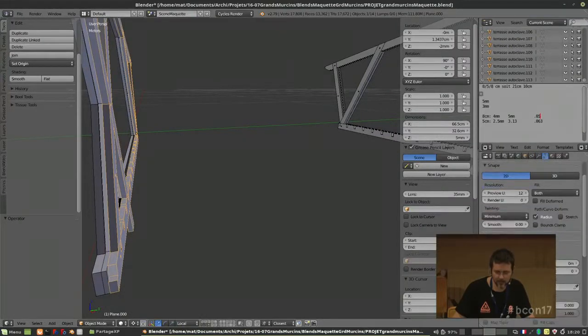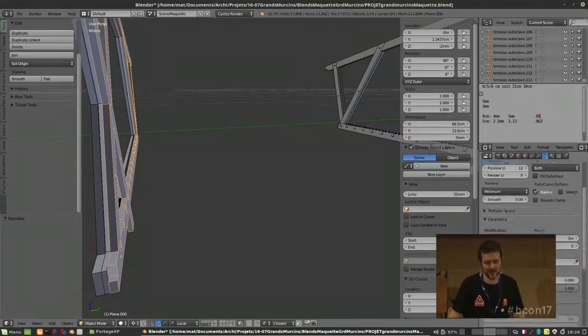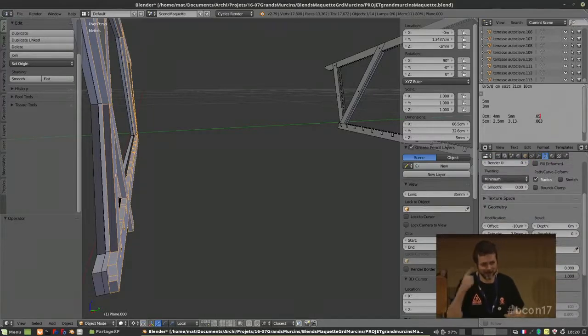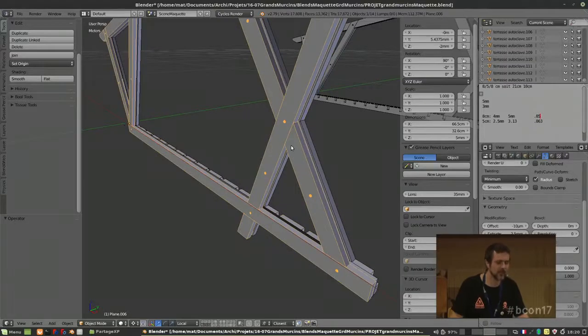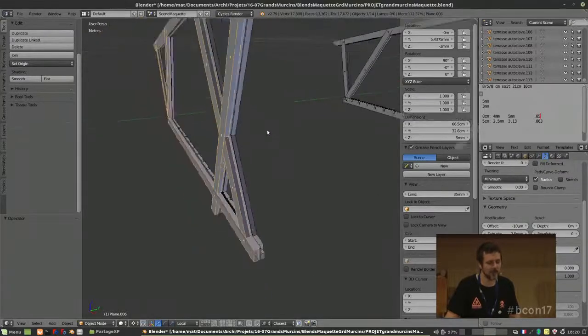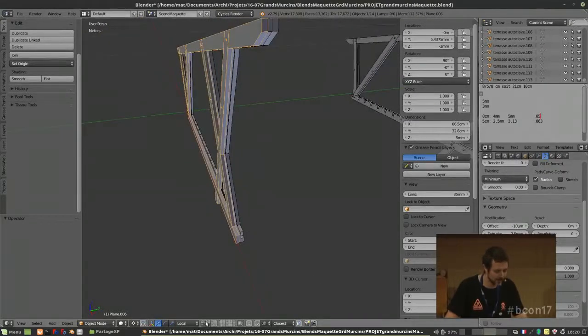With an extrude value here of 2.5 millimeters, because I was cutting in 5 millimeter plywood and extruded the two sides. It makes me mad that every time you have to divide the value by 2, but that's it. I just had to convert everything into curves and check with this extrude that the building was okay.